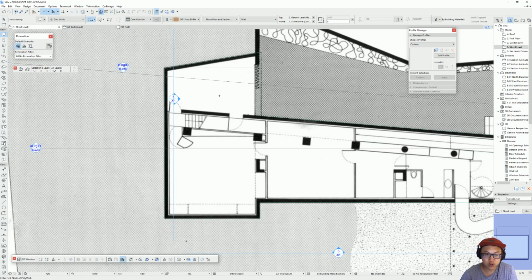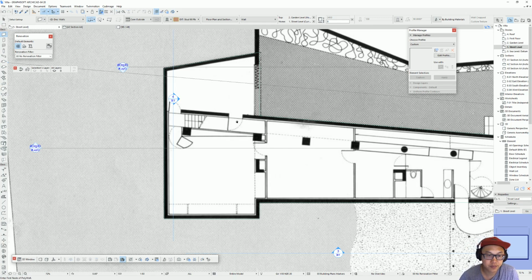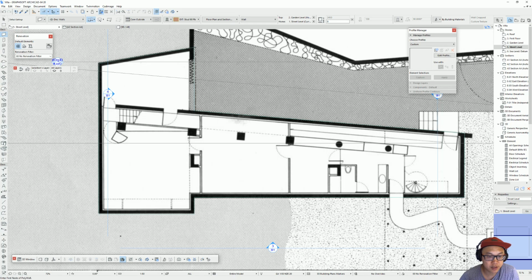I think the first stage is just to get the massing right, and then you can change the wall size, the heights, just to get it started. So now that we got our slab, we know that there's a perimeter wall. So I'm just gonna select the wall tool. Gonna change to a simple composite, a simple structure, and I'm just gonna make it a bit bigger.